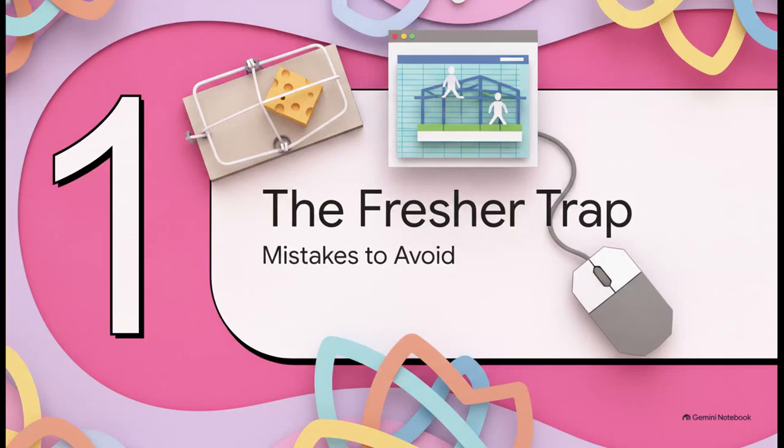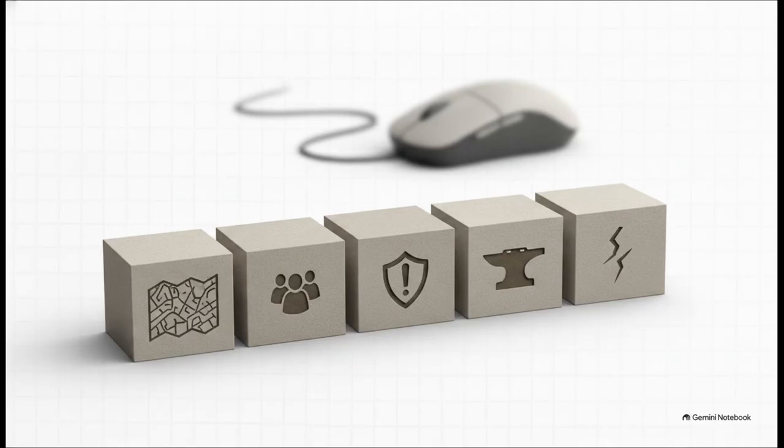Okay, starting right off with Section 1, the fresher trap. The guidance makes it absolutely clear that before you ever even touch a computer mouse, there are fundamental questions you have to answer. What is the adopted building code for your specific jurisdiction? What's the building's occupancy? What's the risk category? What about the seismic parameters for that exact piece of dirt you're building on? Figuring out which document controls which of these decisions, that is the actual job. The software comes much, much later.